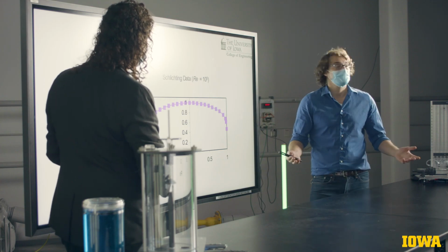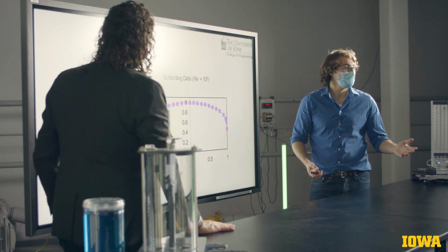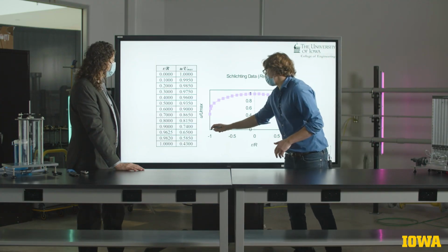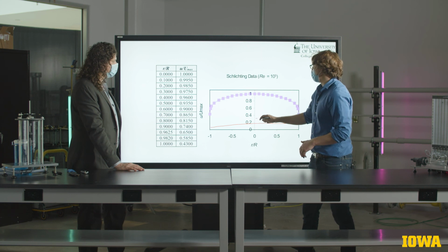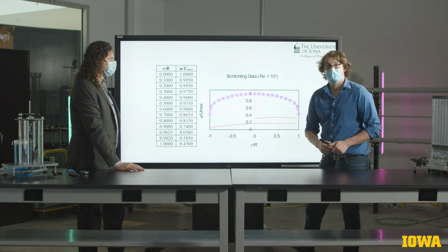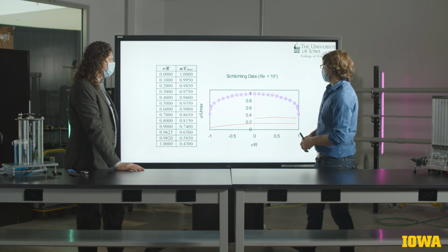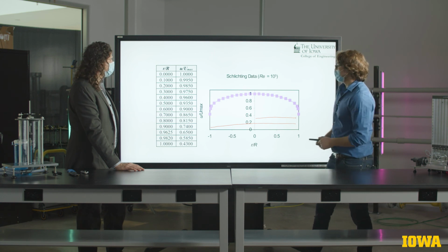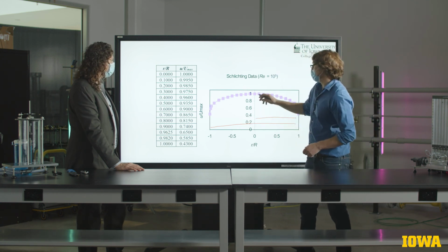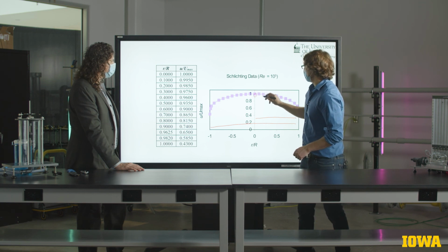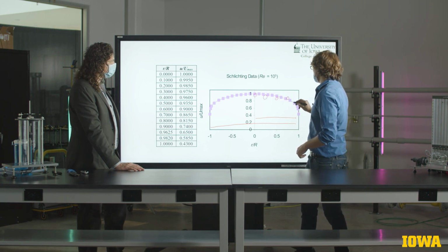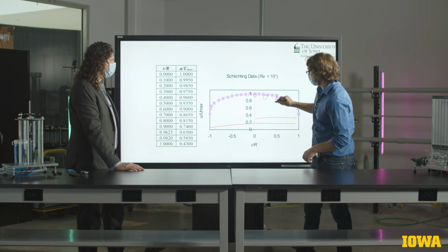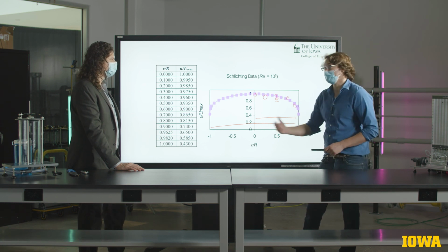The execution of this experiment depends upon the person who is running the lab as well as the experimenter themselves. You may find yourself with data that includes measurements across the entire diameter or simply only from the center line out to the wall. In either case, you should plot your data on top of this sample data from Schlichting, which has been non-dimensionalized by the maximum or center line velocity. And you should have something that fairly closely matches the Schlichting data, especially when you add the uncertainty bars that you calculated using the steps from a few slides ago.